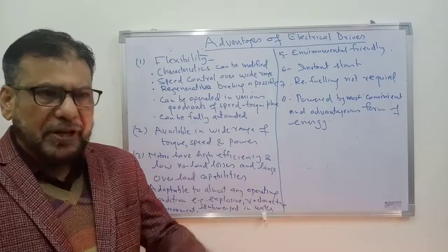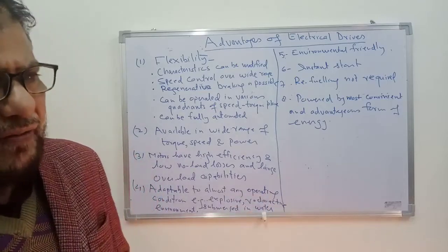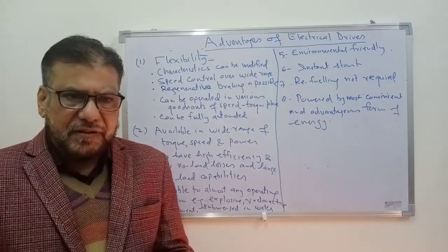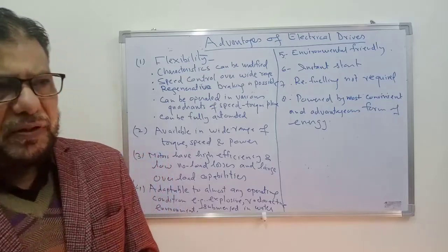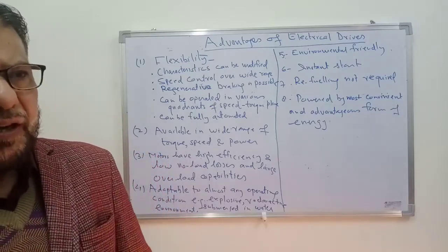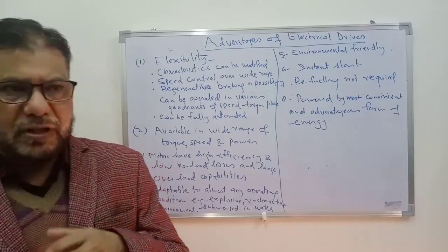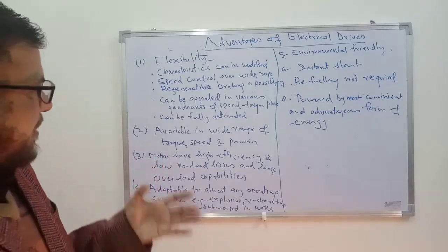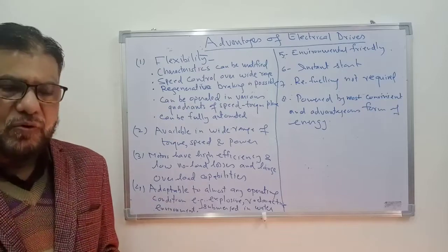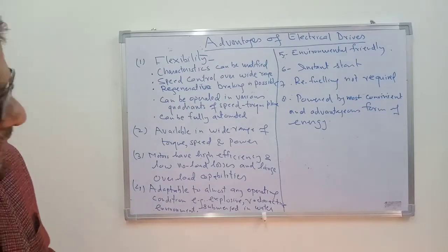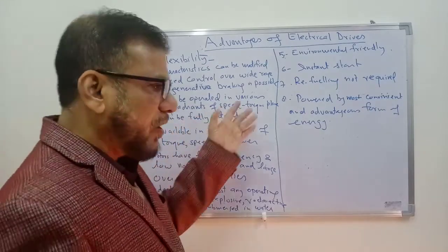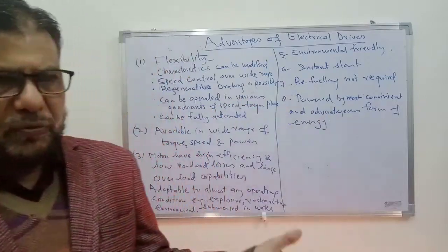That is known as braking mode. And similarly, speed is negative but the torque is positive. So it can be a reverse braking mode. So depending on the situation, depending on the demands, we can use the drive in all the four quadrants of the speed torque plane. This is not easy or not possible for other forms of drives.